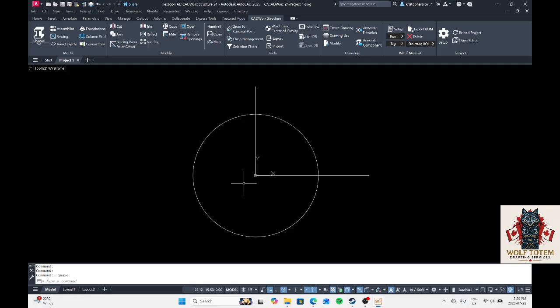So now we drew a couple lines and a circle. The other thing we're going to finish off on this video for right now is we're going to use 2 more commands that we're going to learn. We're going to use the trim command. So we're going to type in TR for trim. And trim is a fun command because it can trim off excess lines. So if we want, we can trim these lines that are sticking outside the circle here.